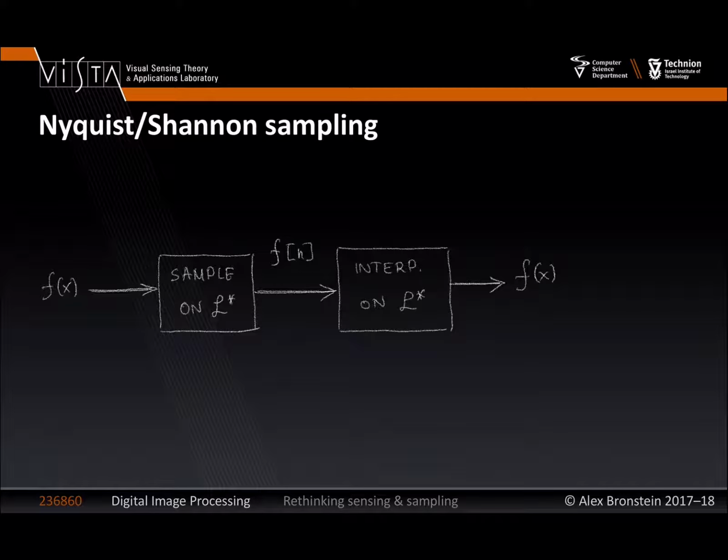Now, let's see what happens if I first do an integer translation of this sequence by this operator tau m. What happens to the result? So if I do integer translation, basically it is by just putting n minus m instead of n in these coefficients. Let's just reindex the sum. So this makes C depend on this n prime. N prime, of course, equals n minus m. And the plus m will pop up here, right?